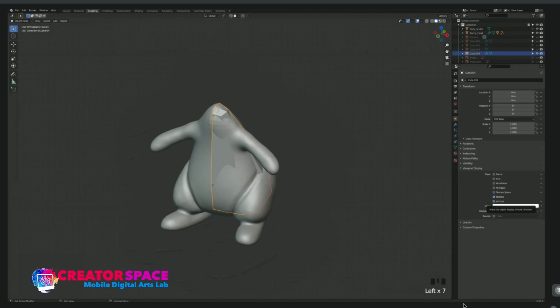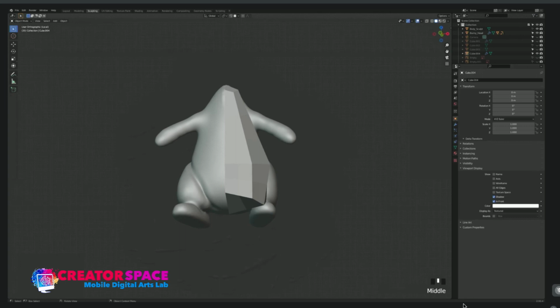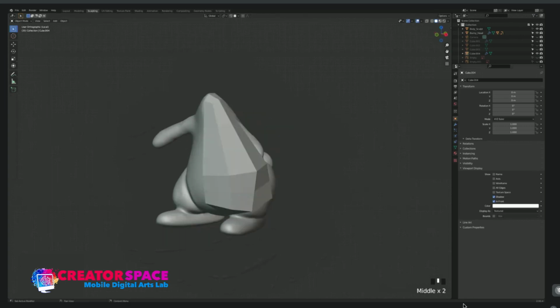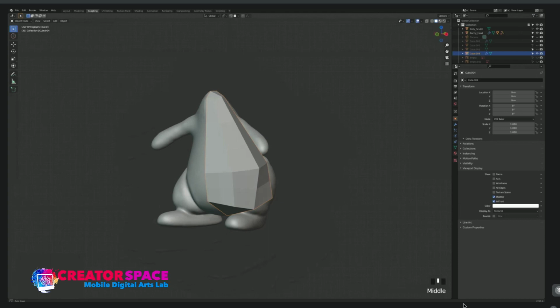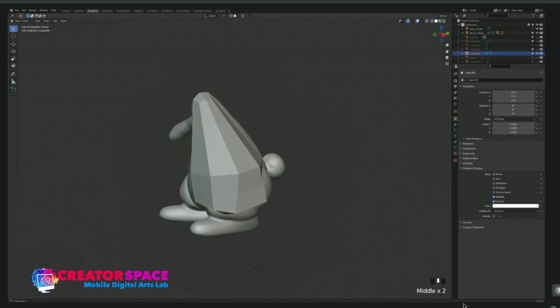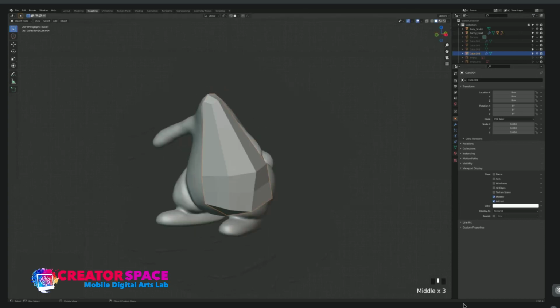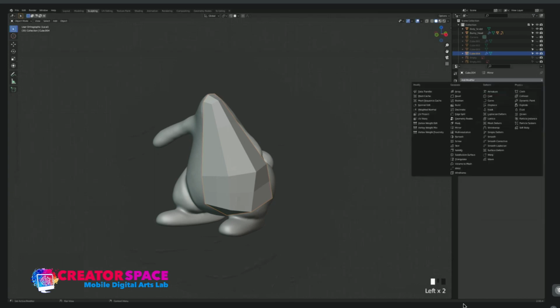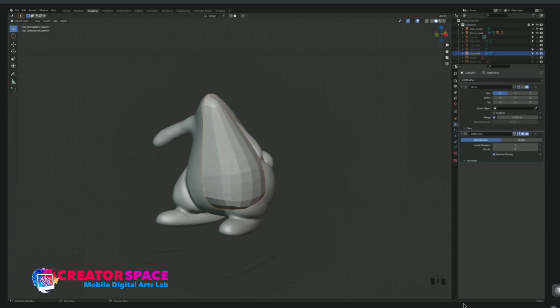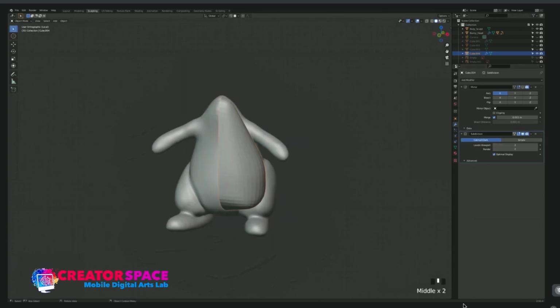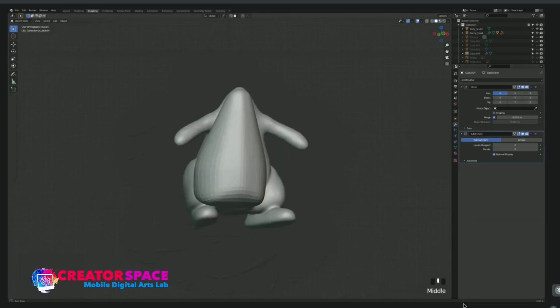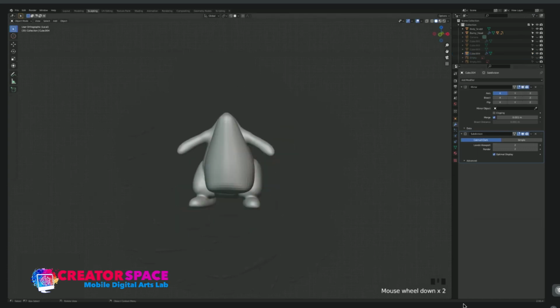I go to in front, so this object is always in front of the sculpt. Okay. So you'll say, well, that's kind of blocky. You don't have that smoothness of the sculpt. Well, don't worry. That's where the modifier goes, and we'll go to subdivision surface, and we'll go to, let's say, 2. That's already smooth enough. That's smoother. If we turn on the mirror, hey, that looks not bad, right?